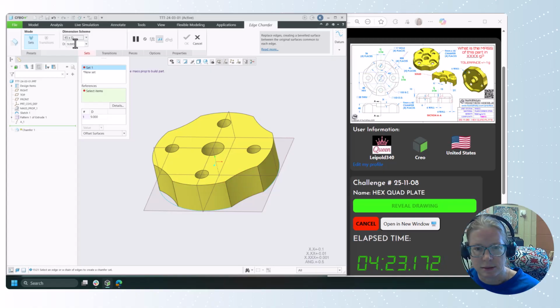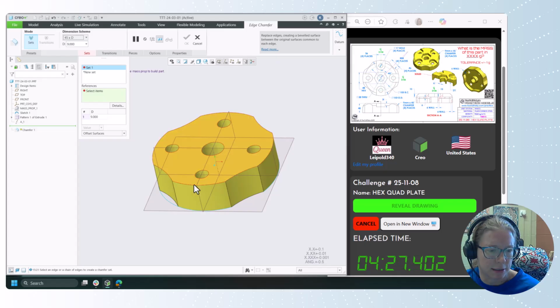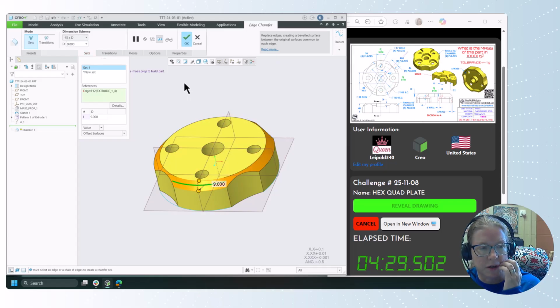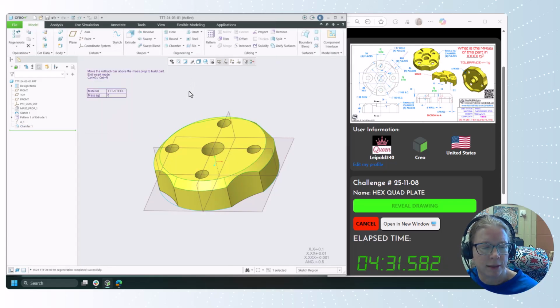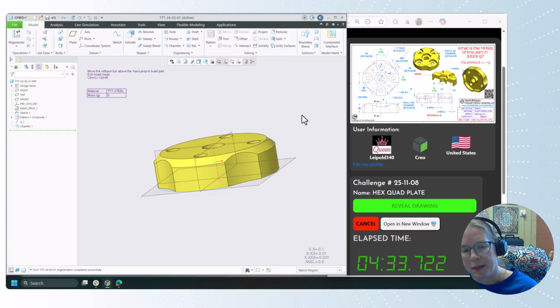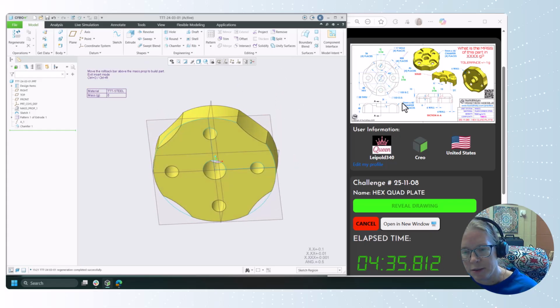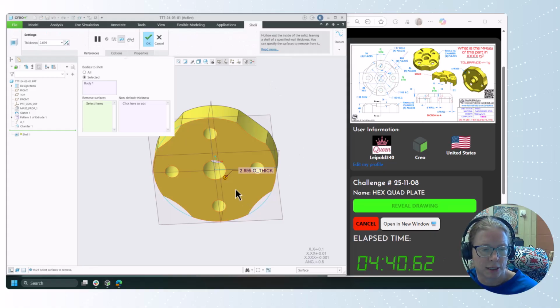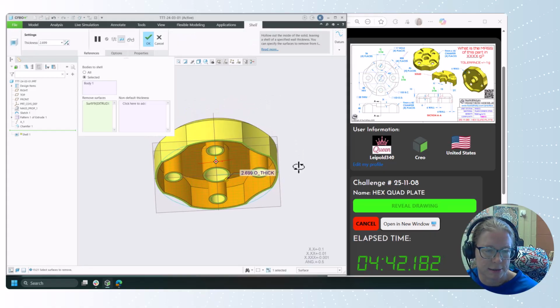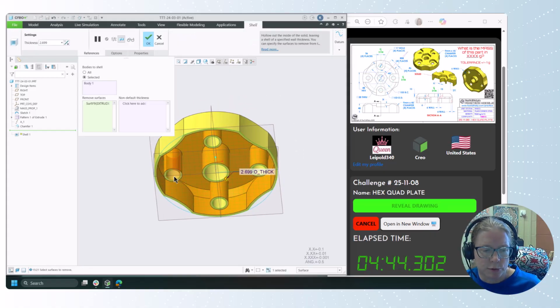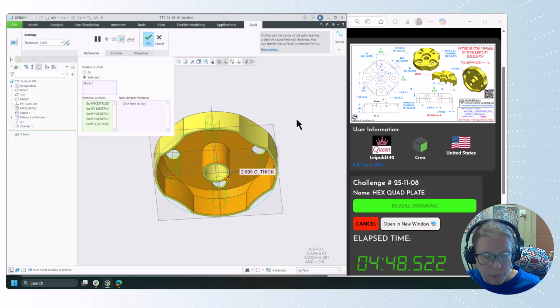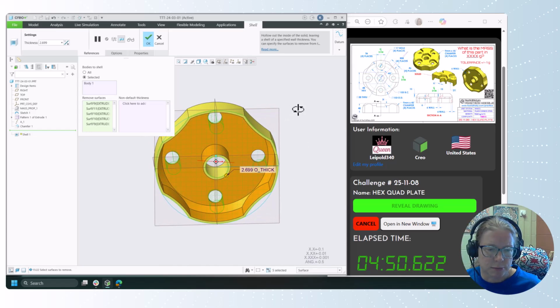The angle dimension on that chamfer is 9 millimeters. So we'll click on one of these edges and it'll go all the way around. Okay. Now, next thing I'm going to do is add the shell. And the shell is going to, I'm going to remove the bottom wall thickness. I'm also going to remove these holes as wall thicknesses. I have to hold down Control to select those multiples.